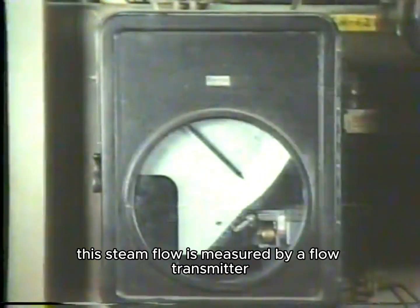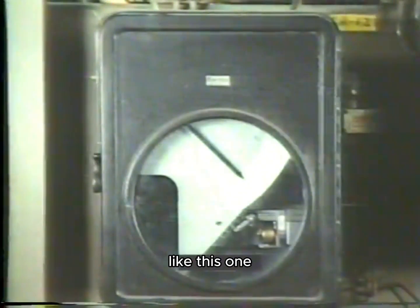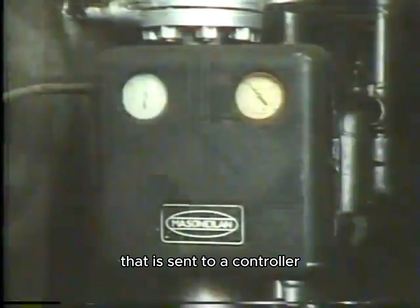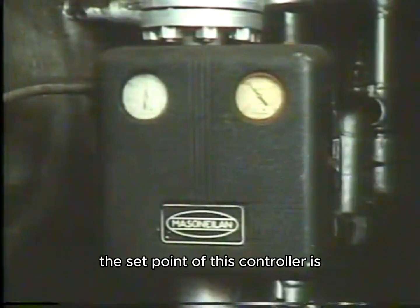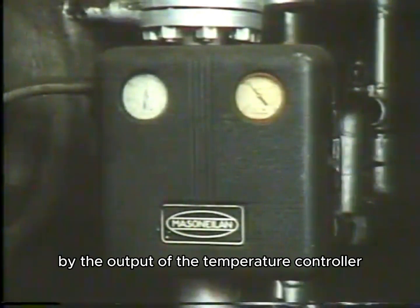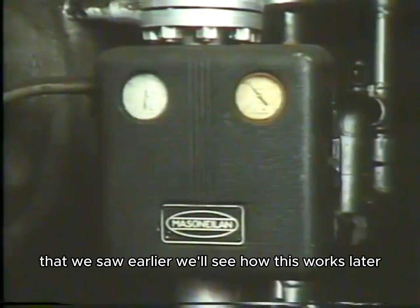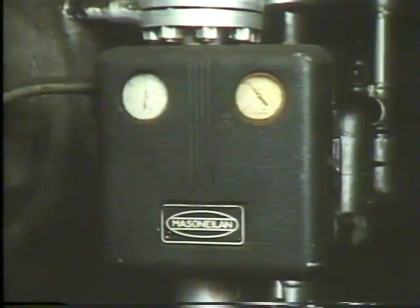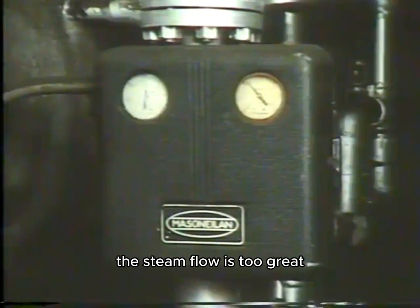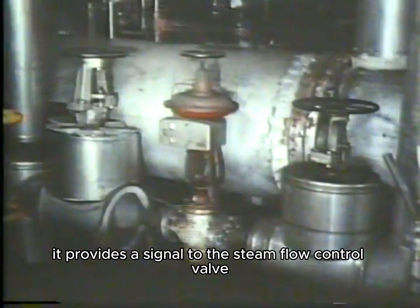This steam flow is measured by a flow transmitter like this one. The steam flow measurement is converted to a signal that is sent to a controller. The set point of this controller is automatically adjusted by the output of the temperature controller that we saw earlier. We'll see how this works later. If the flow controller determines that the steam flow is too great or too little, it provides a signal to the steam flow control valve.